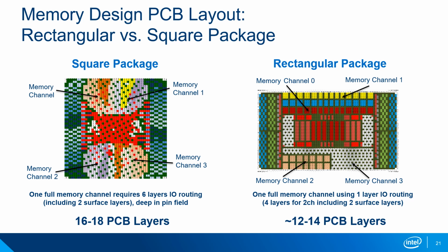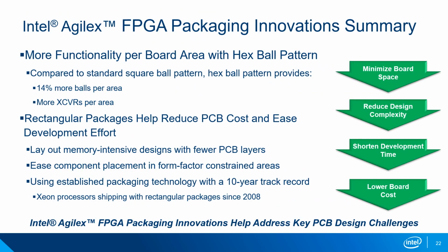Although the rectangular package is new to Agilex, it's not new to Intel. Intel has been using rectangular packages since 2008 to help simplify board layout. The hex ball pattern enables us to get more balls per area, which translates into more transceivers per area. That, coupled with the rectangular package, has allowed us to reduce the number of PCB layers, easing the PCB development effort and lowering the PCB cost.